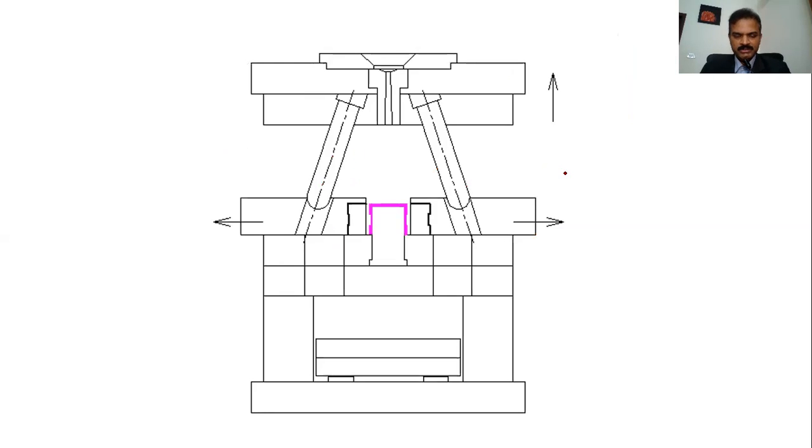See, this is what is going to happen. Now the mold has begun to open. It has already traveled this far. See, the pin, the finger was here. It is moving straight up. Because it is cut at an angle, this is supposed to have a lateral movement, right?